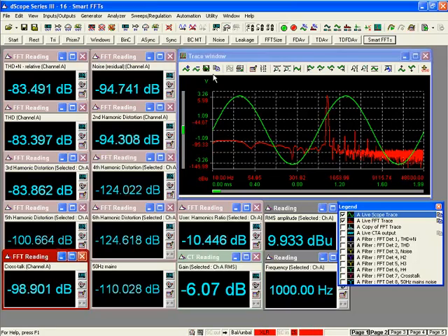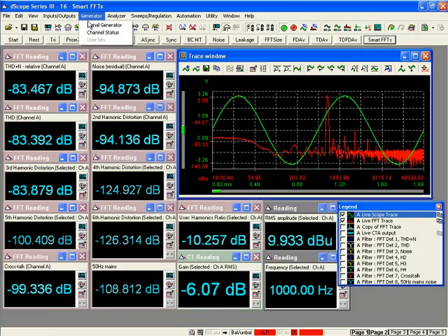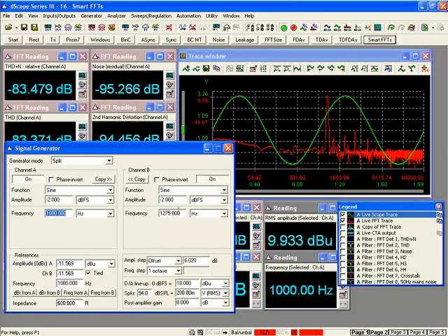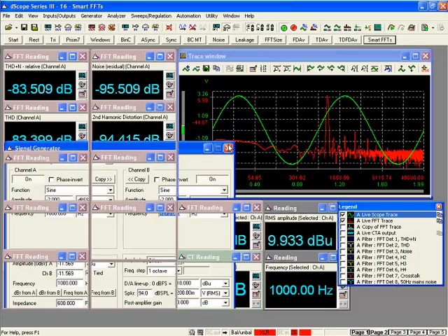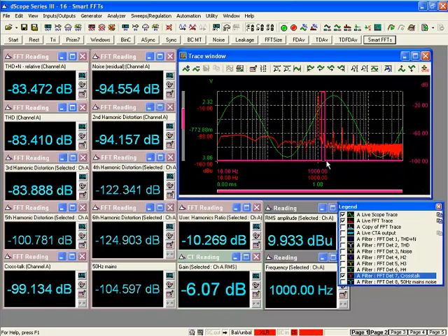I've got a crosstalk reading down here, so in my signal generator, I've offset the tone frequencies from channel A to channel B, so I have a slightly higher frequency on channel B, but the filters are selective enough, because they're true brick wall notches here, to isolate this crosstalk component from the tone component, which is very close in frequency, but we can actually isolate them as independent quantities when both channels are operating.